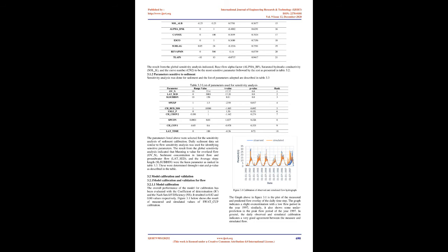3. Results and Discussion. 3.1 Sensitivity Analysis. Sensitivity analysis for both flow and sediment was carried out prior to calibration of the model to save time during calibration. Distinguishing sensitive parameters led us to aim only at those parameters which most affect the model output during calibration, since the SWAT model has a number of parameters to deal with.